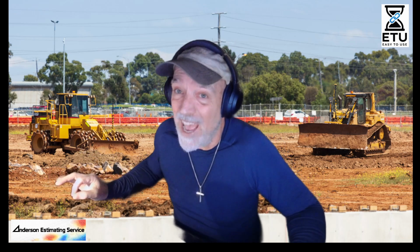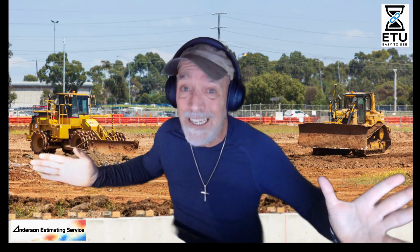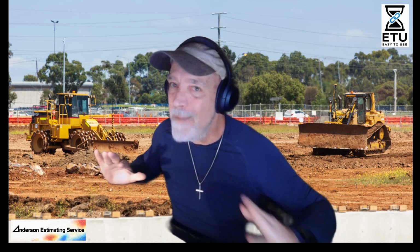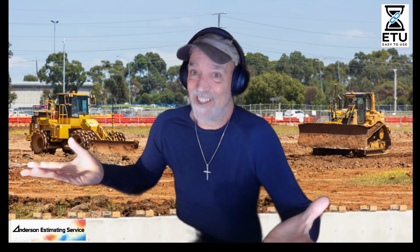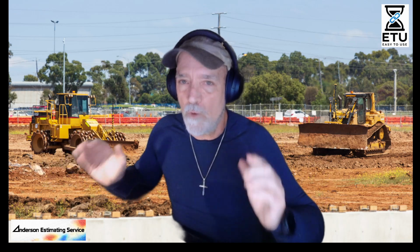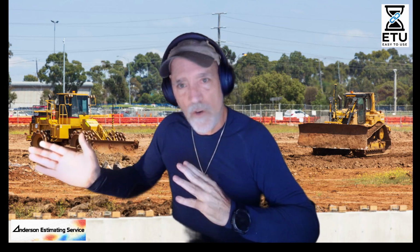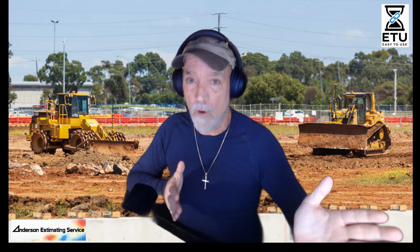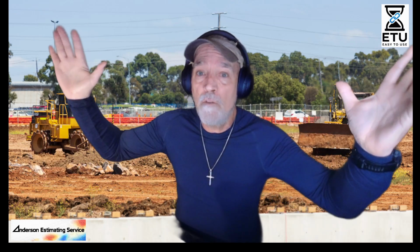It gets really bad when you get on a big project and you overbuild all your pads. You're skewing the import-export. You're making it wrong. Yes, there are other quantities. I'm not even saying that. All I'm saying is when you go to do your volumes, you need to compare that existing surface stripped to the final design strip or subgrade. Those are the quantities for your import or export. That's all I'm saying. Yeah, there's a ton of other volumes.